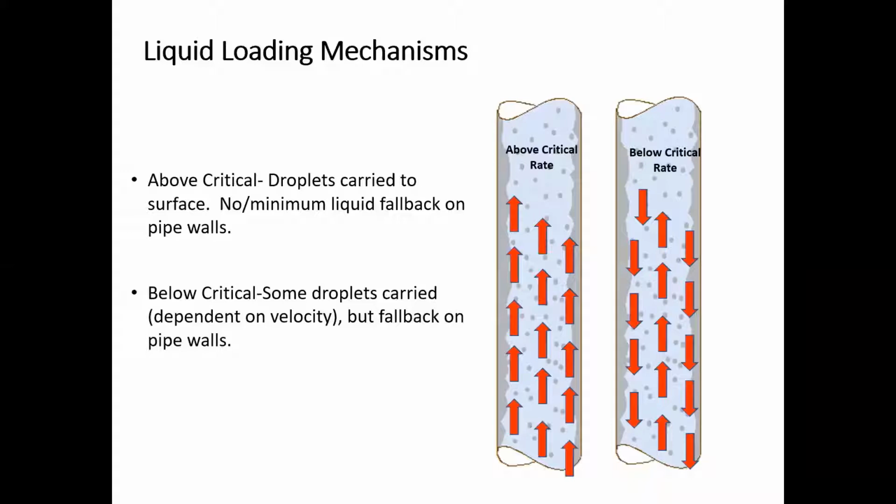Eventually, the liquid fallback from the natural flowing well will load and log off the well, and an intervention like swabbing or nitrogen may need to be introduced.